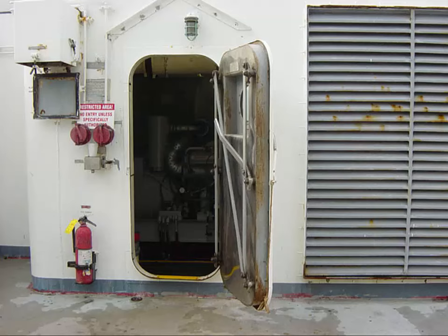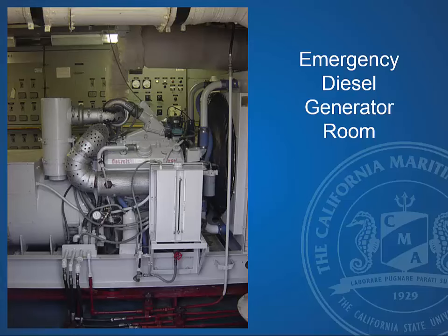Now, one other thing to bring up is that an emergency diesel generator has to be standalone. It has to have everything in that space it needs to operate, and you want it as simple as possible. So it is going to have engine-driven pumps. It will typically be air-cooled with a radiator.